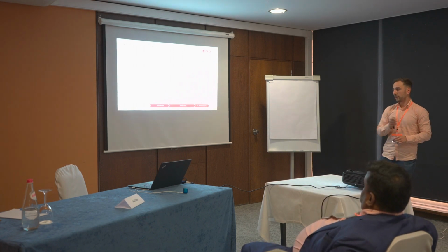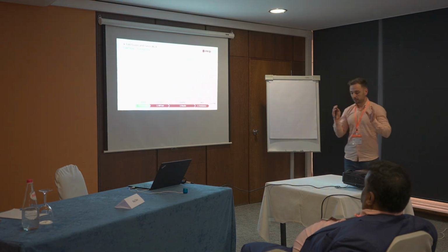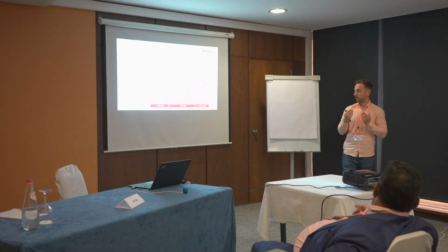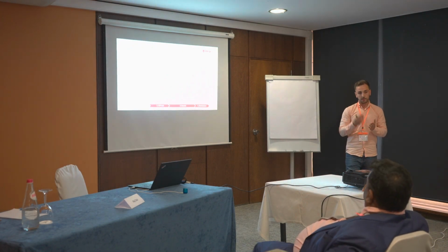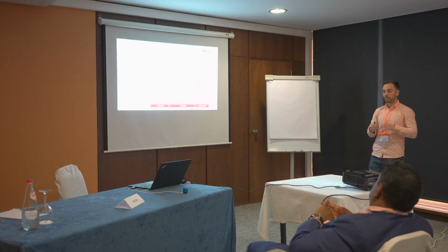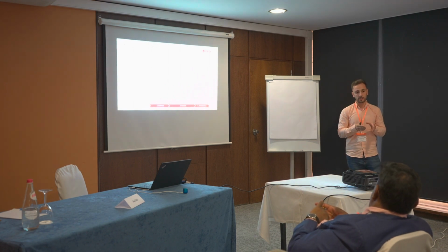Okay, I forgot to mention something important. How can we validate the structure? We have a mannequin with normalized dimensions that, after performing the test, we should introduce into the driver's seat. If the mannequin does not touch any component, it is according to the norm.